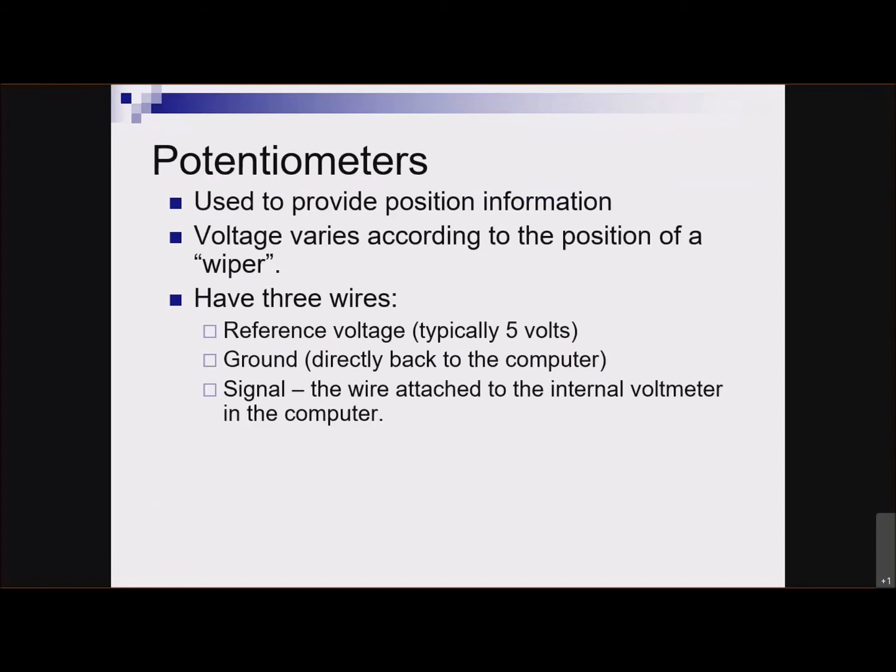Back in the early 80s, when computers were really kind of new in cars, the reference voltage on the Fords and Lincolns that I first looked at was 9 volts, I think. And the trouble with 9 volts is it's too close to the vehicle's battery voltage level. But with 5 volts, you're never going to drop below that when you're cranking the engine or anything like that. So you've always got that 5 volts available to the sensors, and that comes out of a voltage regulator built into the computer.